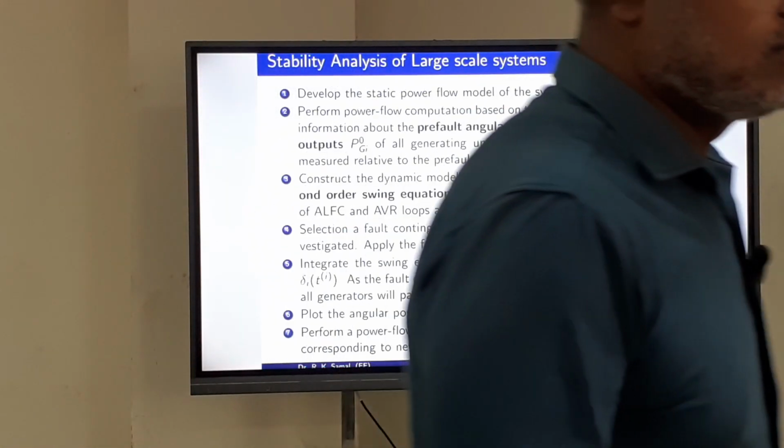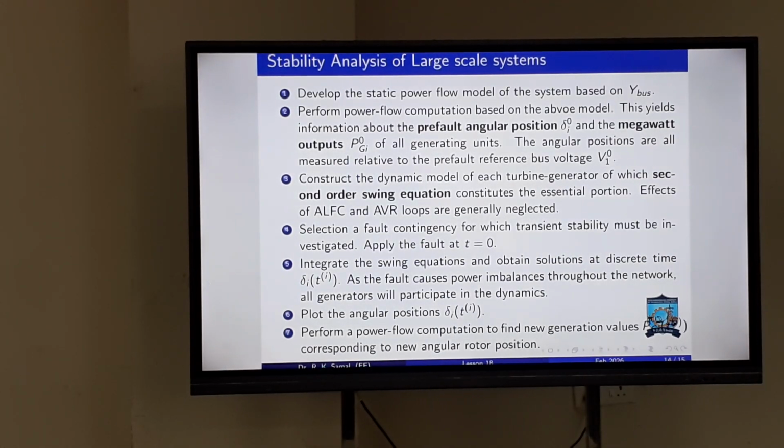First is the load requirement at the different buses. In a 30 bus system, which is a standard system, the load will be given for all the 30 buses. And in that system, I think there are 41 transmission lines. So you need R and X for the transmission lines. Otherwise, how will you create the Y bus? If you see MATPOWER, you might have downloaded it. I have created a video for this experiment, where I have mentioned how to download MATPOWER and how to put it in the MATLAB workspace, or Octave, it also runs in Octave.